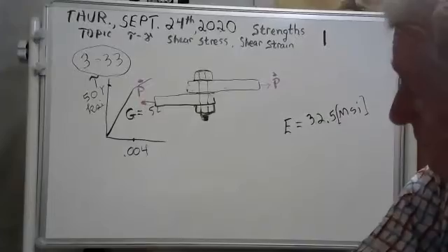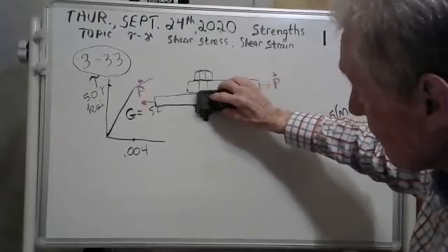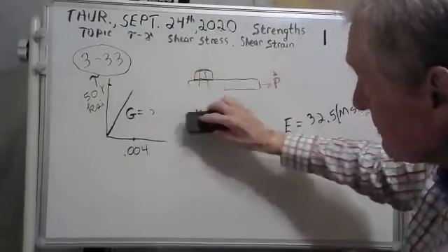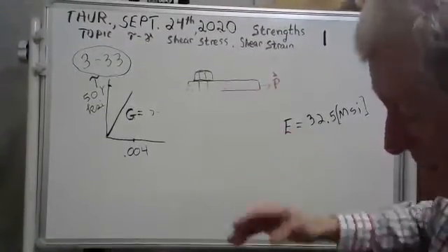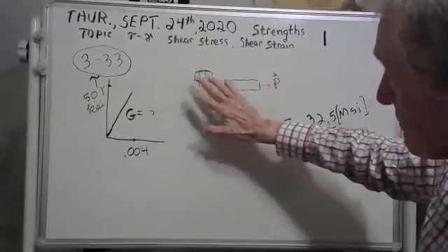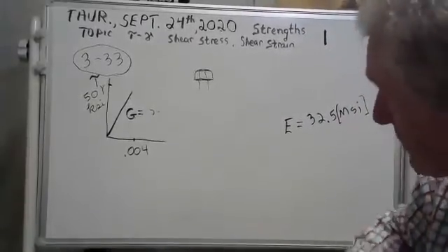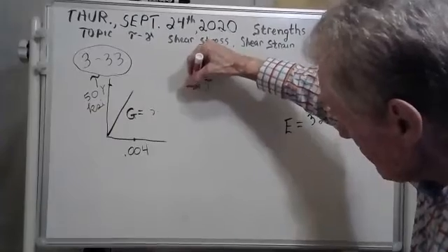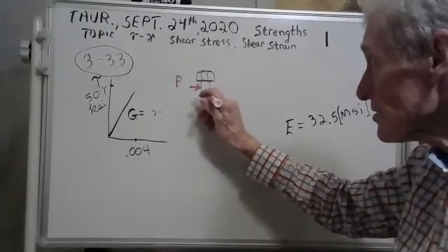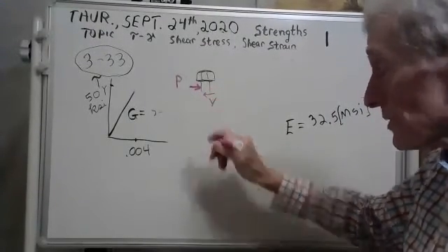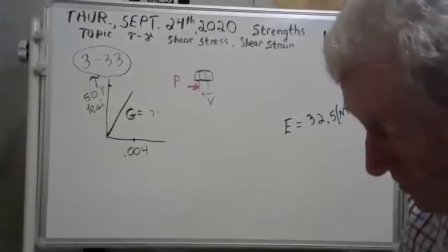So what we're going to do is we're going to section this bolt. And we're going to just forget this bottom part. We don't need it. And we're just going to look at the bolt. Never mind the plate. But if you just look at that bolt, the bolt has a bearing stress acting on it going this way, equal to P. And so therefore, it's got a shear stress, which this book uses the symbol V for shear stress, which would equal P, of course.